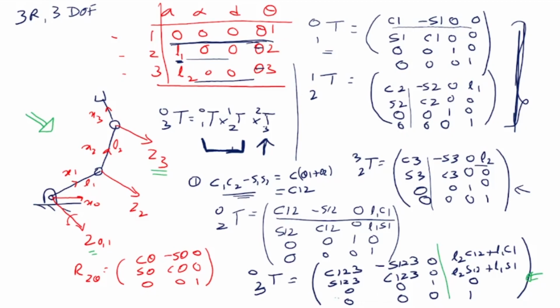This is a homogeneous transformation matrix which consists of 4 parts. This is always 0, 0, 0. This is always 1. So all the matrices you see have 0, 0, 0, 1. It can't be anything different. If it becomes different in a program or somewhere, you immediately know that there is a mistake. It cannot be. Now, this is the rotation matrix, this part.